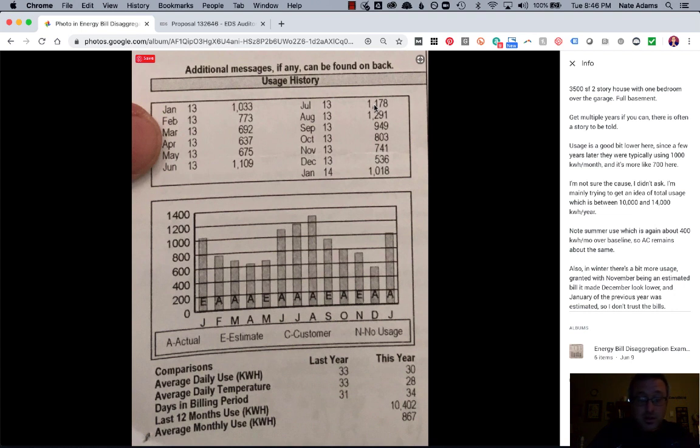It really doesn't. Where you can justify more is if you use a heat pump, so that instead of the system running 3 months a year, it's running 9, 10, 11, 12 months a year. All of a sudden, you can justify a better piece of equipment. Plus, you can justify the better comfort that will come along with that. But in general, if you're looking at just the numbers, SEER 13, that's all you should really be recommending. It really is.